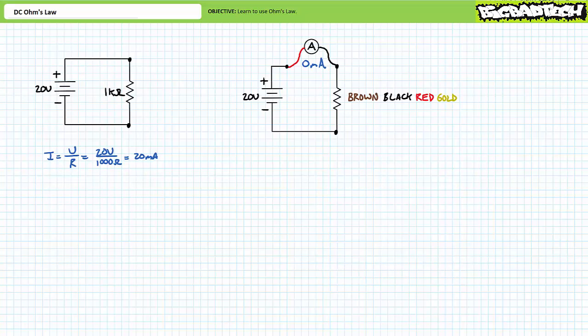However, are it and the ammeter the only elements in the circuit with this source, or is there something else in series with it? Think about what I'm asking. What is something with an infinite resistance? Something with an infinite resistance is an open or an incomplete circuit. This is where intimate knowledge of your circuit building environment, typically a protoboard in lab, comes into play. You may have the correct voltage, and you may have the correct resistor, but a complete circuit may not exist because of an inadvertent open.